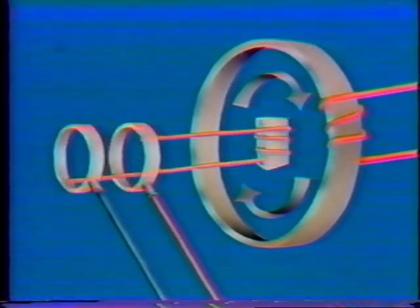The rotor in this generator completes a cycle each time both a north pole and a south pole pass the winding. Remember, in this generator, the field rotates, not the conductor. Each time the north pole of the field passes the winding, the peak positive voltage is induced. As the south pole passes the winding, the peak negative voltage is induced. Voltage is induced in the winding, and from there, current moves on into a circuit. The speed of the rotor in this generator determines the number of cycles it completes each second. A complete revolution of the rotor every second means a complete cycle every second, because both the north pole and the south pole of the rotor pass the winding during that time.